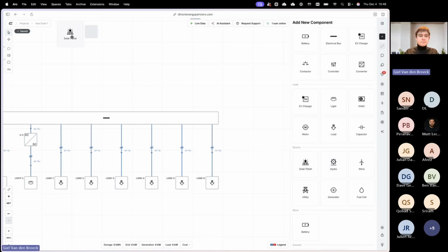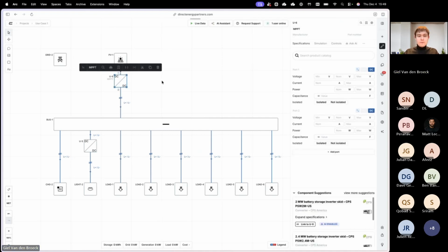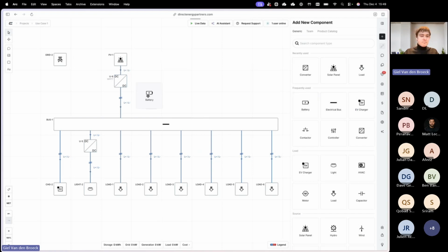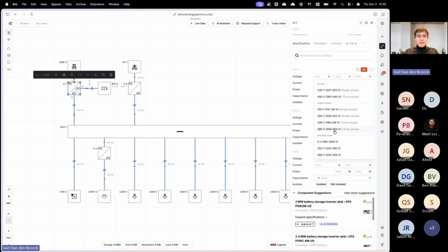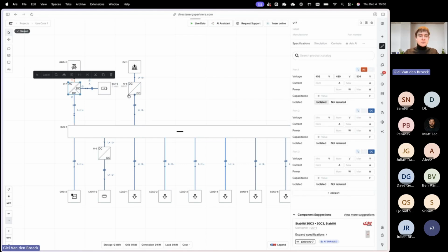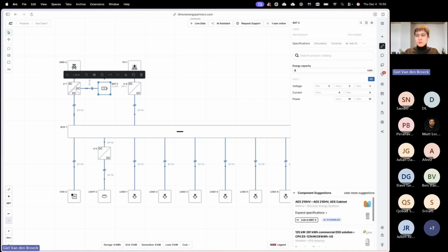And we had solar involved. I'll draw that up here with an intermediate DC-DC unit for maximum power point tracking. And a battery storage system. The battery storage system is connected to a power converter, which has 3 ports. It has an AC port to connect to the grid, being a 480 volt AC connection, isolated from the DC side. And on our battery side, we had a 40 kilowatt hour battery system, operating at around 400 volt nominal.